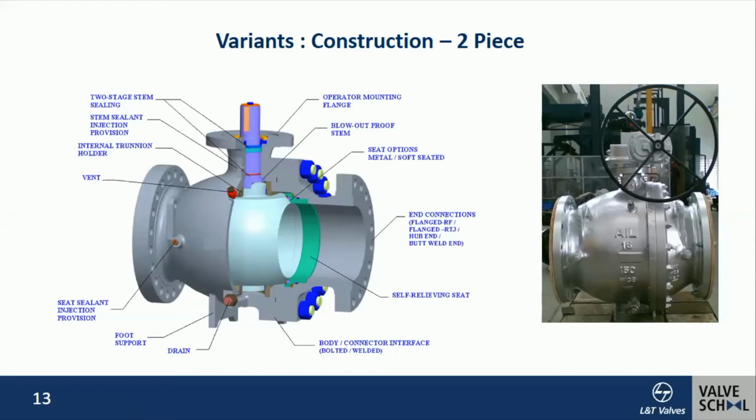These valves could be either with flanged ends or butt weld ends, and the typical stem drive is on the ball. The stem drives the ball through a quarter turn. So this is basically a quarter turn valve, which by means of that quarter turn could be moved from a fully open to a fully closed condition, or vice versa. There are various seat options, as I mentioned. And the valve body is also provided with a cover flange over which any sort of actuation can be mounted.